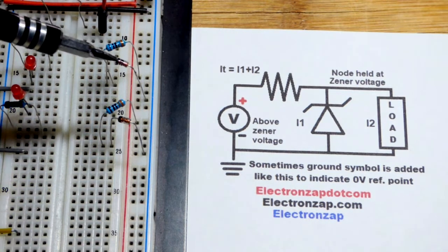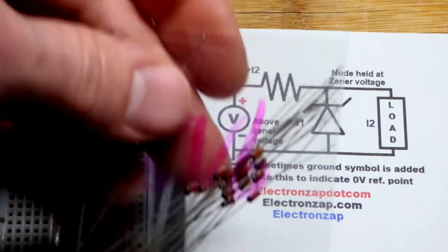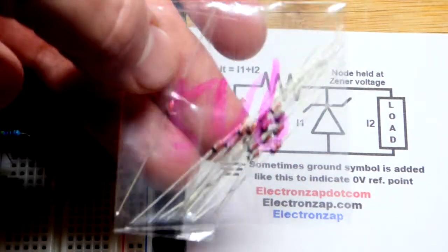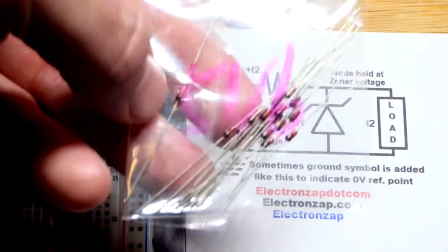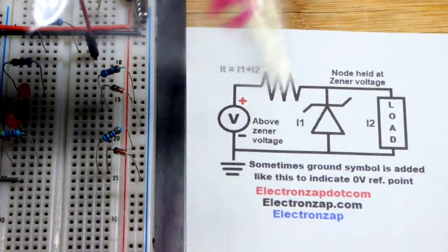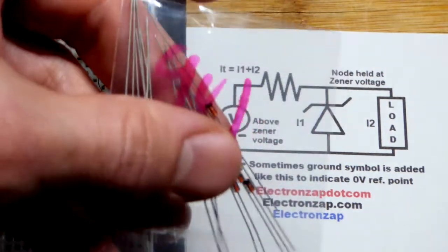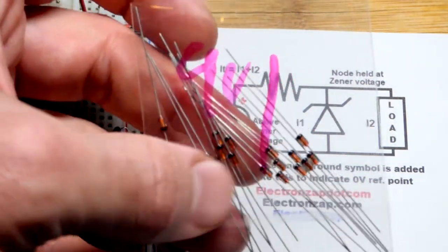And they come in different voltages. On top here, I have a 5.6 volt zener diode, so they use 5V6. V is in place of the decimal point because you wouldn't see a decimal point there. I ordered these from China, cheap. And I also got zener diodes in the Jono's Electronics semiconductor kit, and that's at 9V1 for 9.1 volt.